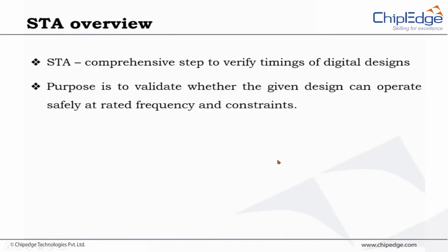So functionality and timing. So that's why I strongly think always that your design verification and your static timing analysis sign off are the key things to prove to you that you're ready for silicon. Your design verification is going to tell you that your functionality is good to go. And your STA person is going to tell you that your timing aspect is good to go.